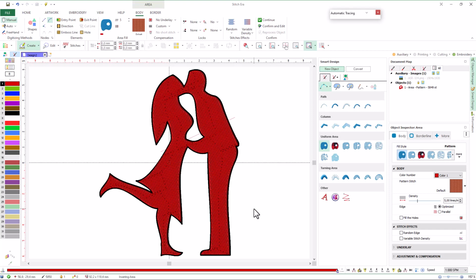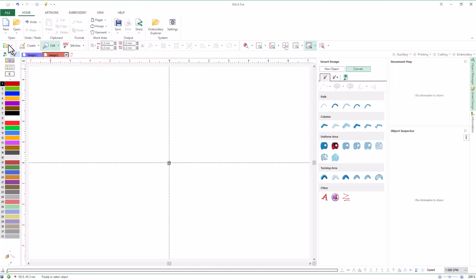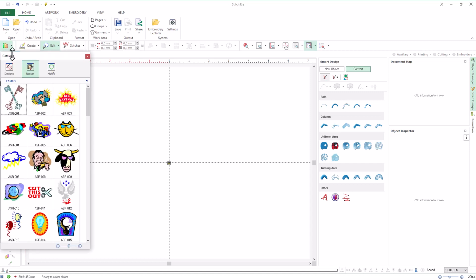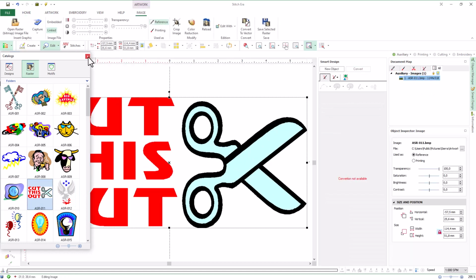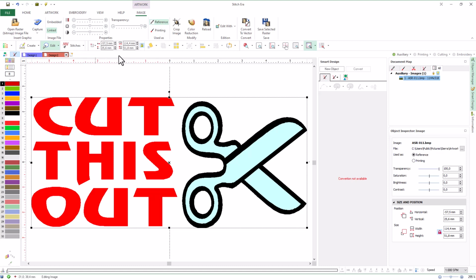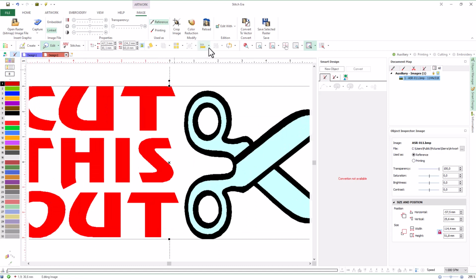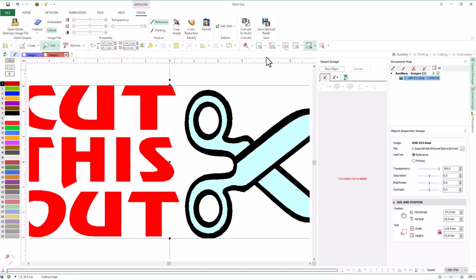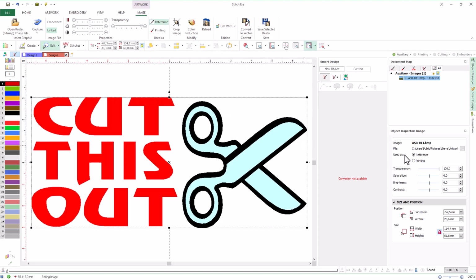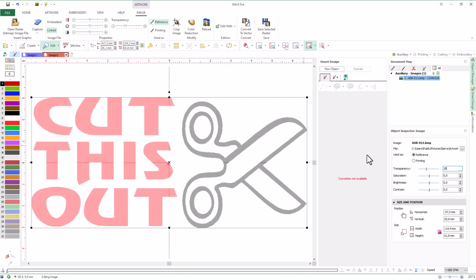So, let's create another new design and try with another image to explore the tool further. We will select an image that allows us to use auto trace with turning areas. Using the Rescale command, we will adjust the size so that these segments become about 7 mm width. Then, we center the image and assign some transparency using the Object Inspector to improve the visibility for our embroidery objects. Finally, we lock the image.